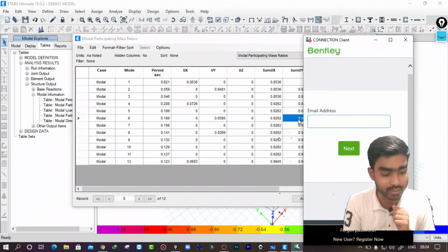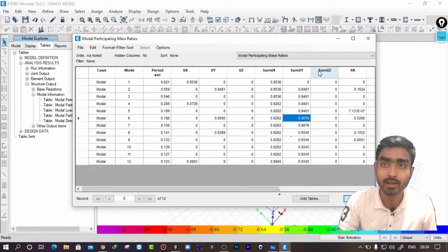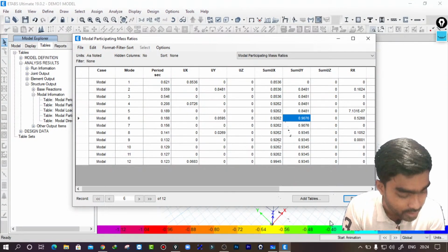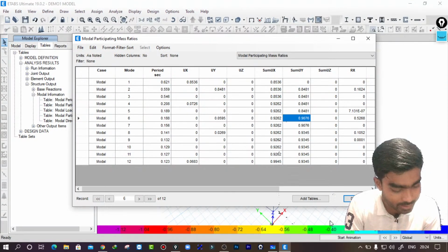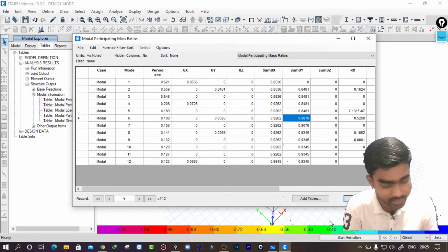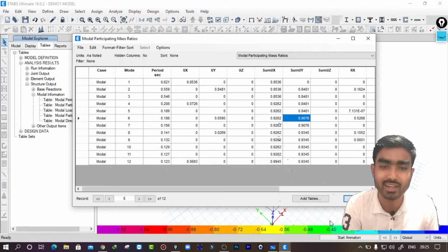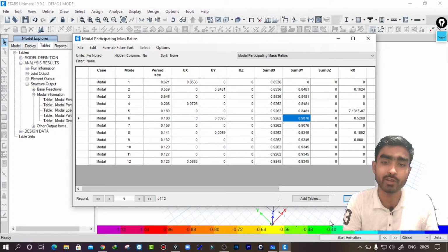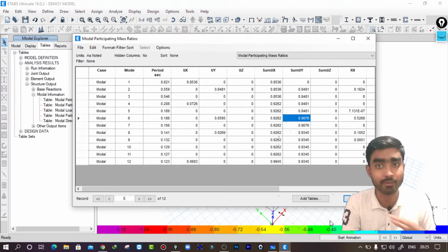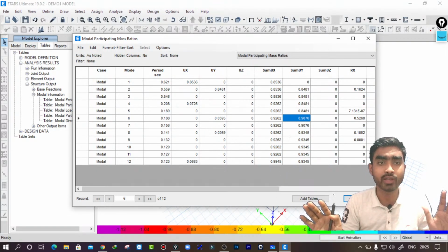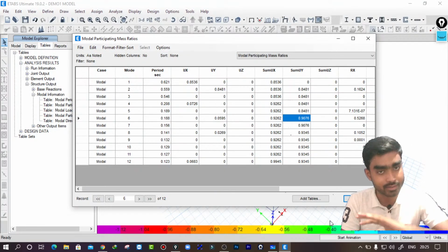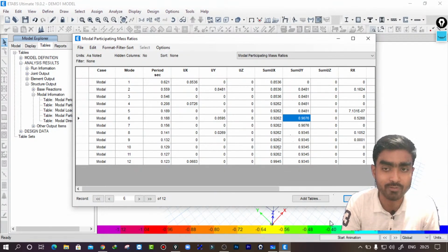Yes, Mr. Siddiqui sir is also right. The rigid diaphragm is also provided to calculate the center of mass. As I have told you already, the rigid diaphragm also represents the center of mass of the structure. If there is a water tank on top of the staircase cap or roof slab, what to do there? Please do not model this water tank in ETABS itself, or in the same model itself. Better you provide the water load on the slab and the wall loads on the beams, just to consider the loading, and design the water tank separately in another file or another model.